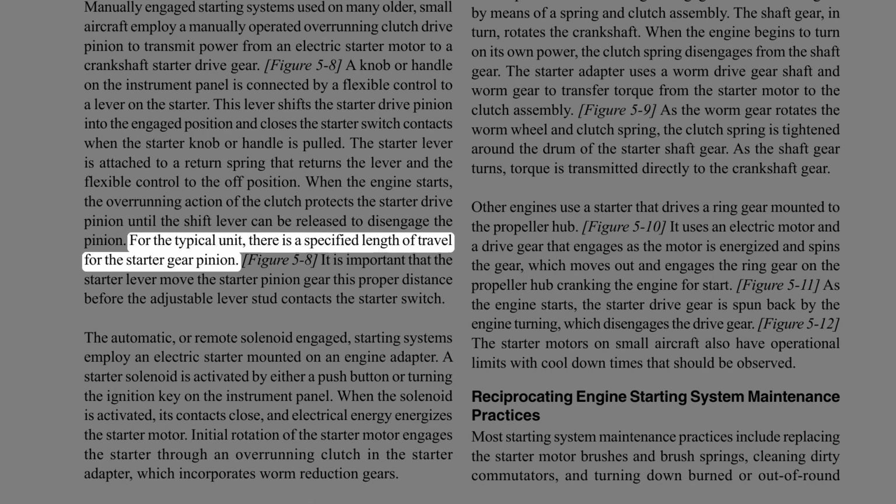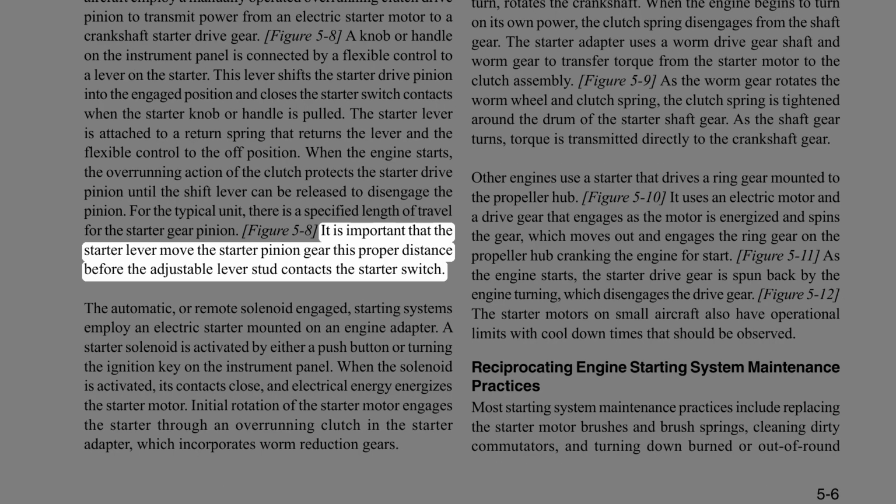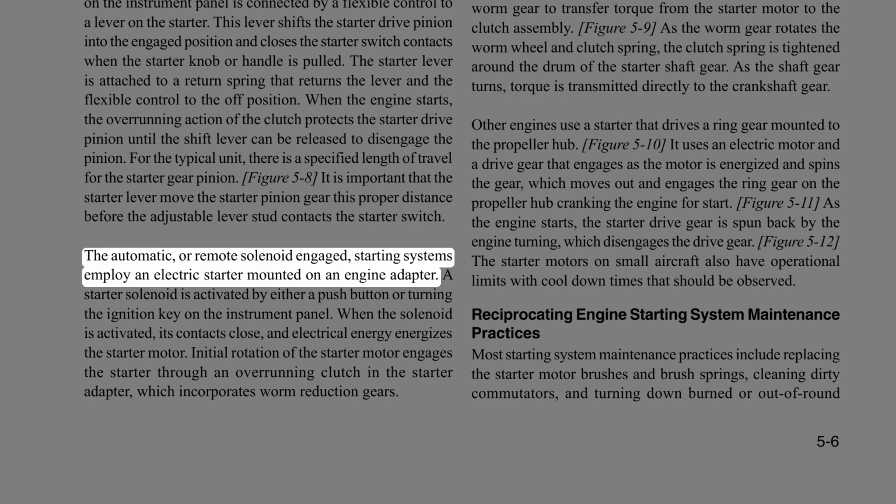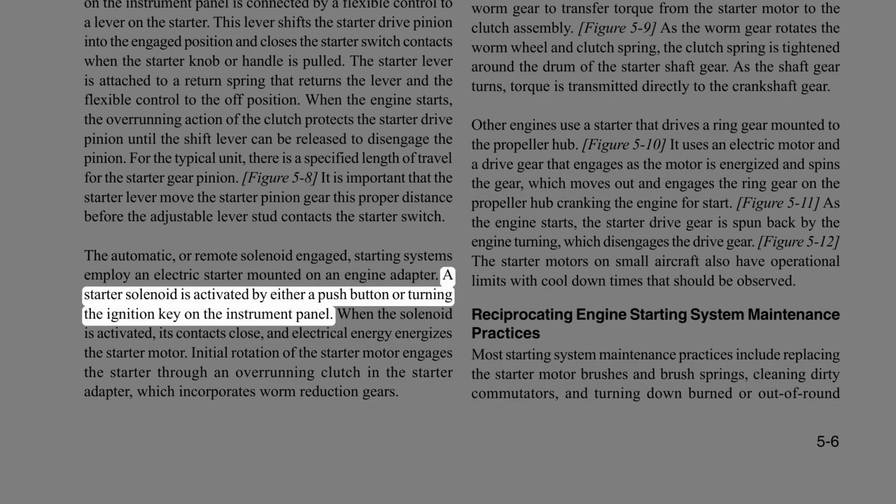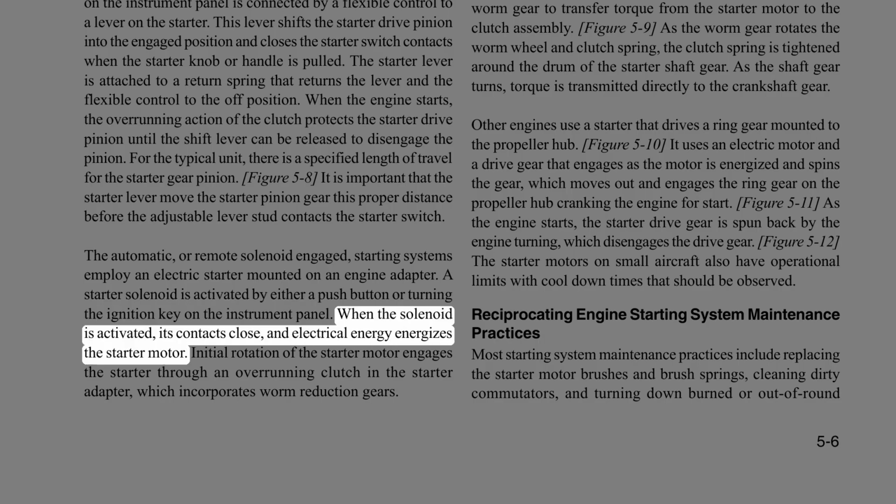For the typical unit, there is a specified length of travel for the starter gear pinion. It is important that the starter lever move the starter pinion gear this proper distance before the adjustable lever stud contacts the starter switch. The automatic or remote solenoid engaged starting systems employ an electric starter mounted on an engine adapter. A starter solenoid is activated by either a push button or turning the ignition key on the instrument panel. When the solenoid is activated, its contacts close, and electrical energy energizes the starter motor.